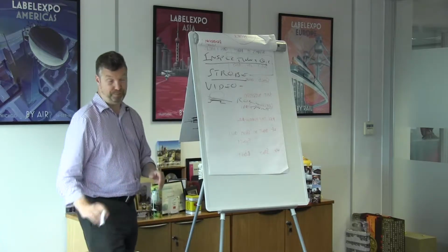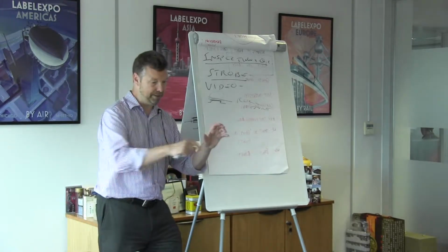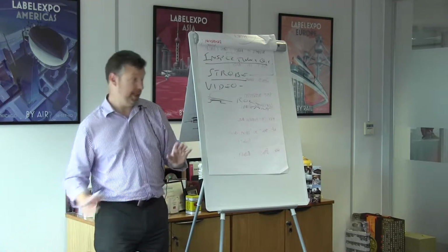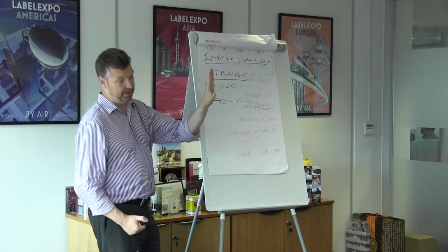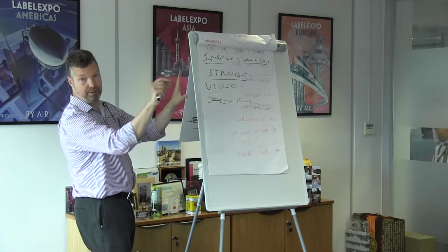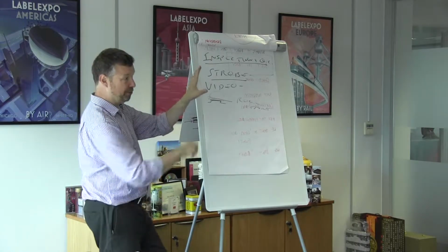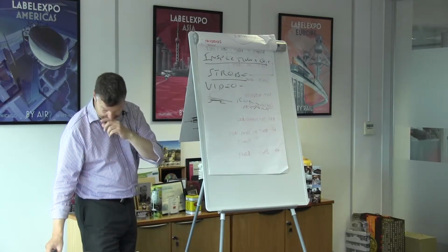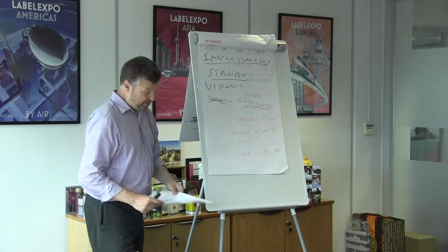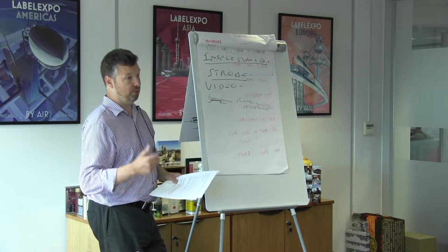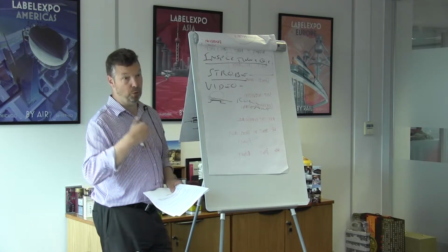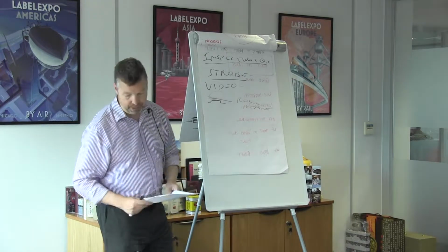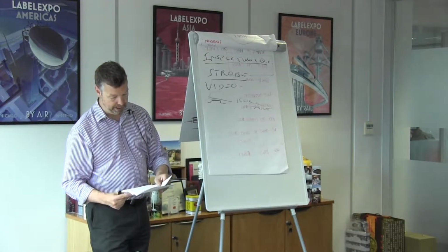Whereas before, it would have been the press operator manually moving the camera over, almost by hand control, now the PDF comes up and the pre-press operator just puts marks where they want the camera to patrol, if you like. Patrol this area, patrol that area, patrol this area. Then the camera automatically moves around to those areas. So what this means is that we can now control variable information, and we can now control all the text, because the camera knows exactly what text it has to be looking for. Okay, so that's the PDF.